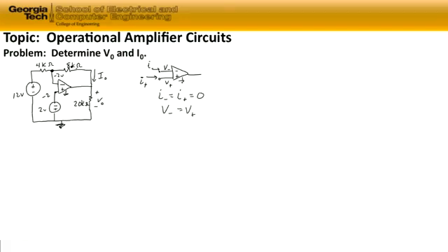The way we do that is we use Kirchhoff's current law, and we'll sum the currents into this top node that we've identified as a node at minus 2 volts. If we do that, we will come up with an equation which gives us Vout as the unknown.